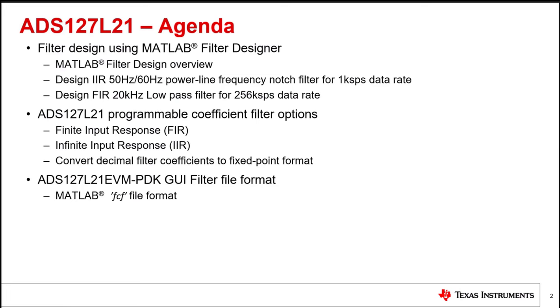So real quick, on this presentation, which you can find later and download for offline viewing, the agenda right now, we're just going to focus on this first section, which is really the nuts and bolts of how to go through the process of using the MATLAB Filter Designer tool to create a custom filter and then download it to the ADS127L21. These other two sections are really just supplemental backup material that you can look at later to better understand how all of this is implemented inside of the actual ADC itself.